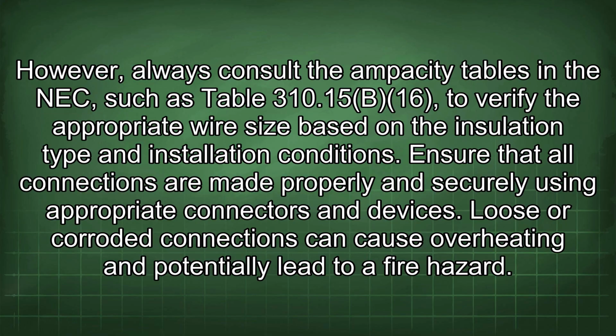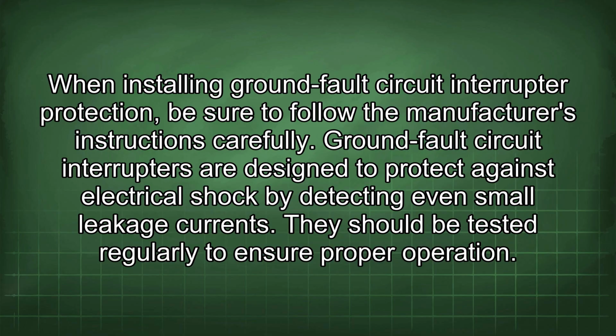Ensure that all connections are made properly and securely using appropriate connectors and devices. Loose or corroded connections can cause overheating and potentially lead to a fire hazard. When installing ground fault circuit interrupter protection, be sure to follow the manufacturer's instructions carefully. Ground fault circuit interrupters are designed to protect against electrical shock by detecting even small leakage currents. They should be tested regularly to ensure proper operation.